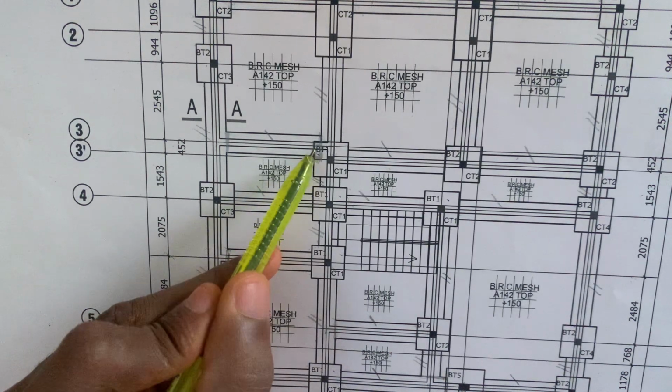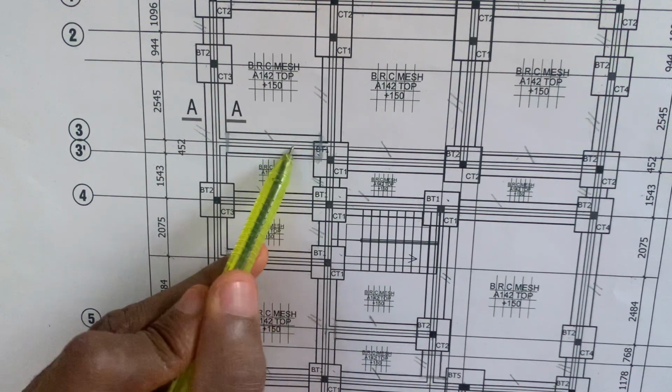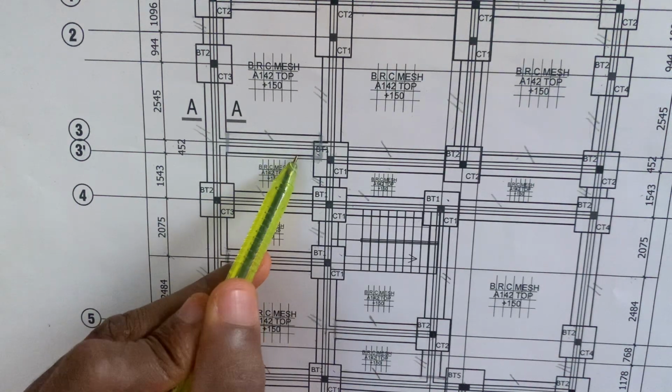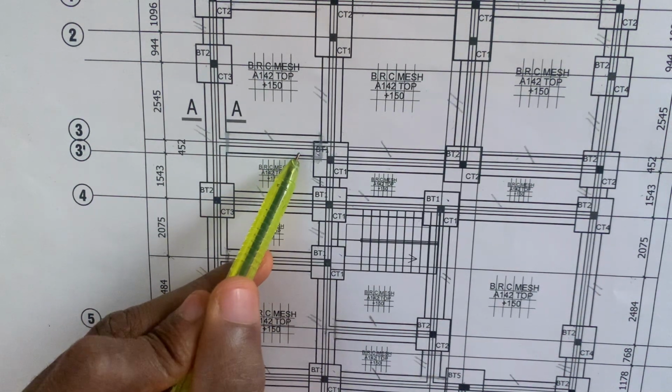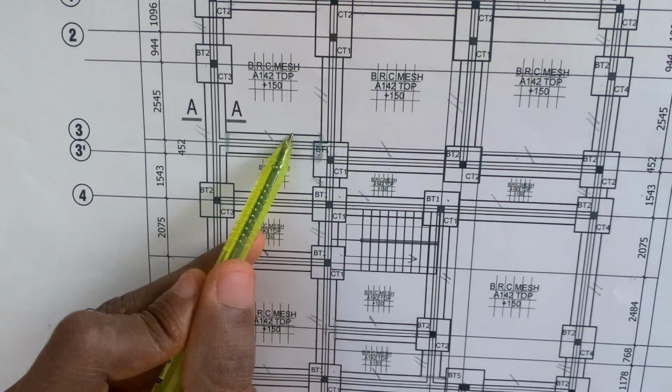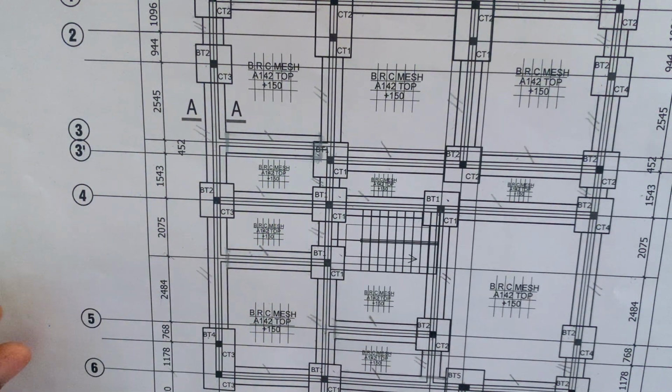If you look closely, from here to here is the combination of the thickness of this blockwork and half of the spread here. To get the width of our foundation trench, you first find the thickness of the blockwork and then add twice the spread, and twice the spread is like saying the thickness of our blockwork times 2.